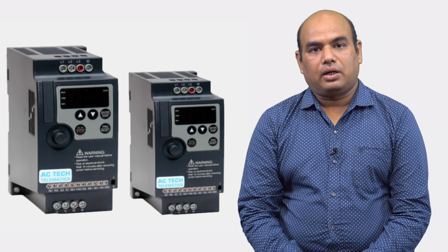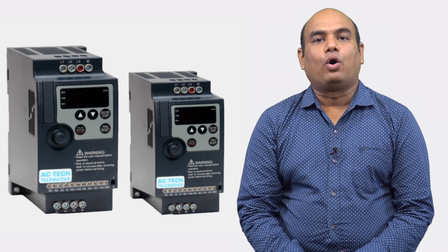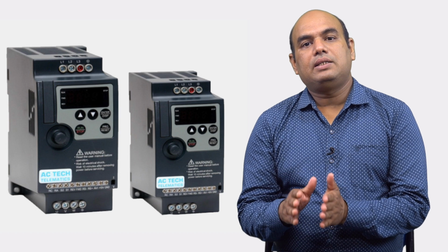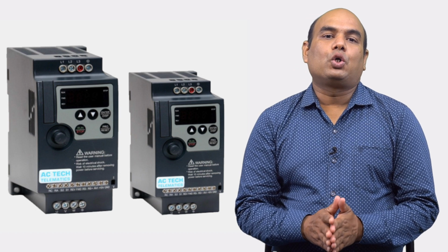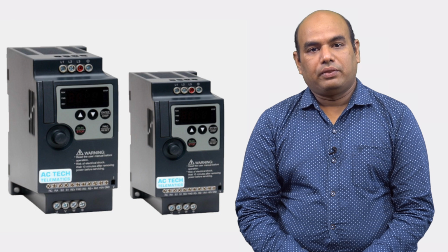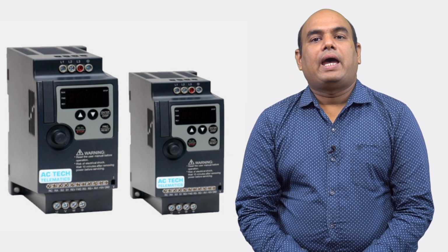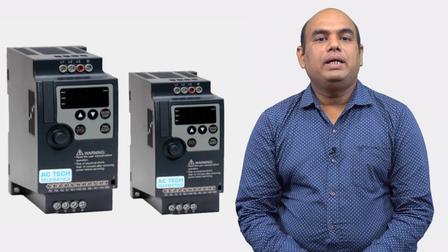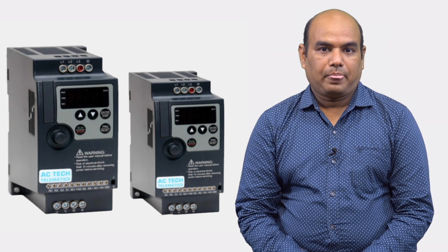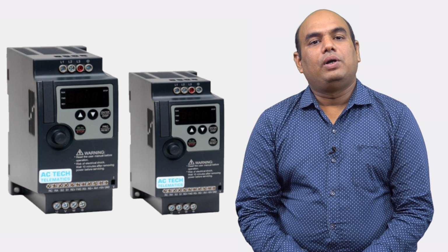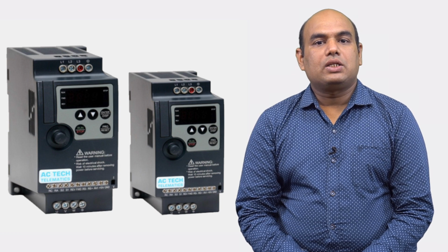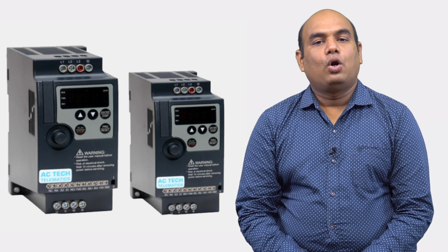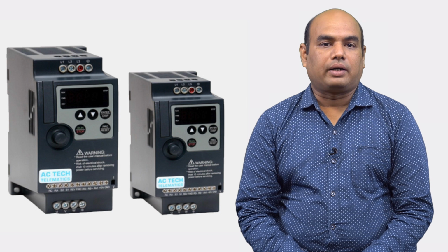When the inverter frequency is reduced to make the synchronous speed less than that of the motor speed, the machine works as a generator. The power flows from machine to DC link and DC link voltage VDC reverses. If the fully controlled converter shown in the figure is made to work as an inverter, the power supplied to the DC link will be transferred to AC supply. The regenerative braking will take place. Thus, no additional equipment is required for regenerative braking of current source inverter drive.